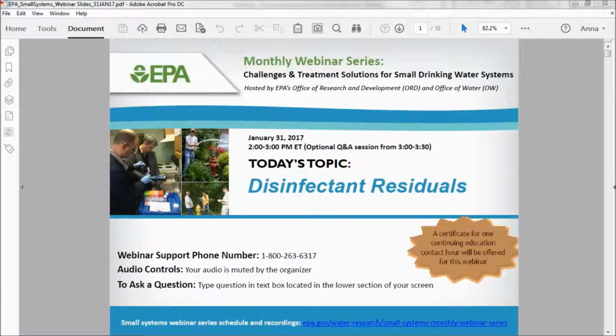This is from Matthew. How do bubbles bias the sample results? Do they bias them high or low? Both bubbles and condensation in sample cells will bias high, so you'd have artificially higher results.